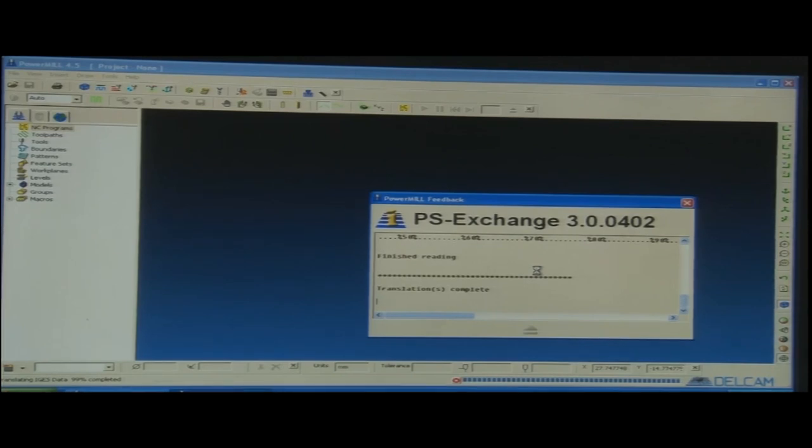When we have to use that on a CNC machine, it has to be taken care that Z should always be in the tool direction. The other format is STL format. STL is generally used for additive manufacturing, because it considers the whole triangular mesh as one body. All triangles are merged into each other, so it is generally used in 3D printing. So, STL, IGS or DXF are the common input files that can be taken in this.